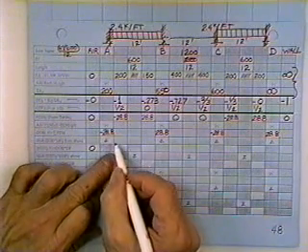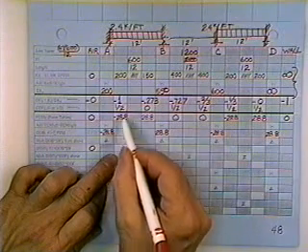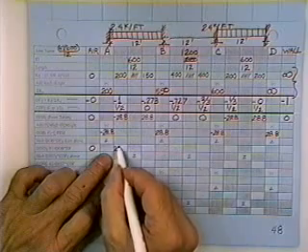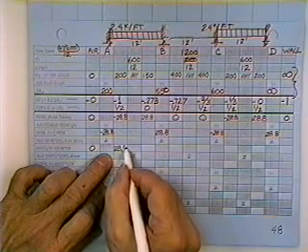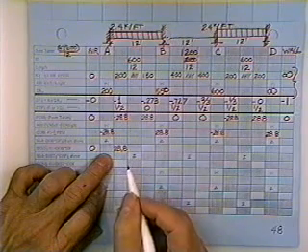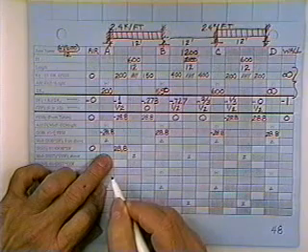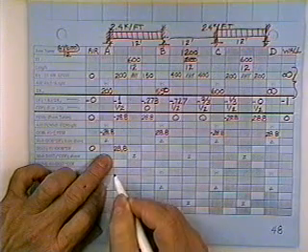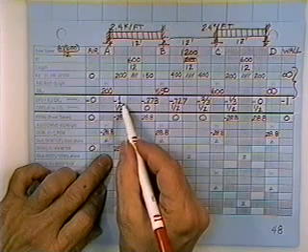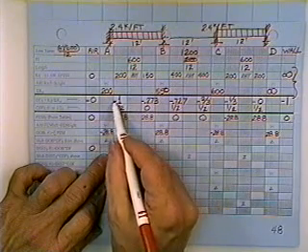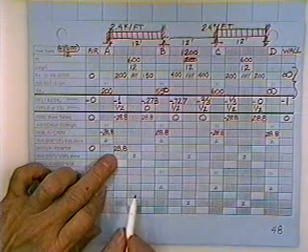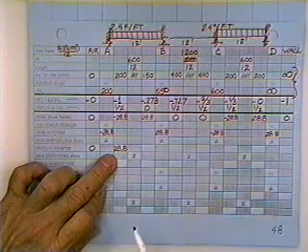To find out how much goes to the right of the joint, you multiply the minus 28.8 times the distribution factor given above. That's positive 28.8. Now, most books won't tell you the distribution factor is a minus 1, because it's really not. It's the fact that he lets go of the 28.8 that changes the sign. Not truly, because you multiply it times the distribution factor. The only thing is I can never remember to change the sign. So if you put the minus on the 1, you'll see 28.8 times a minus 1, and you'll get a plus 28.8. It's what happens when he lets go of the wrench.